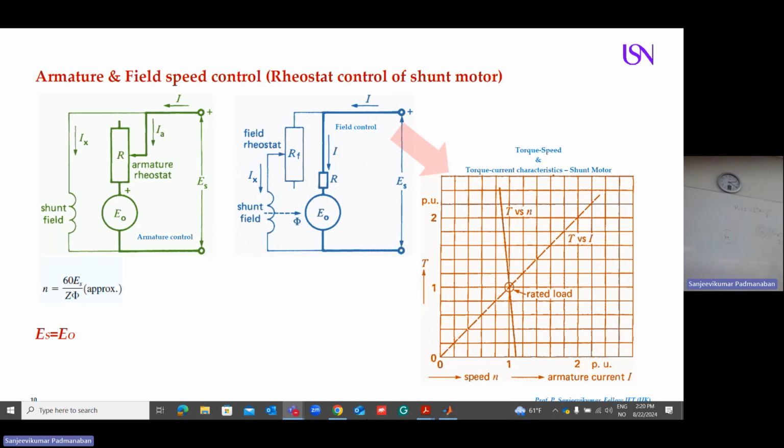So usually the no load current will be like 10 to 15%. It is not zero. It means you are going to have 10 to 15% load by itself. Then the remaining you are going to load externally. Is it clear to you? So that's why in the beginning, your current rises very high due to the kickback effect.